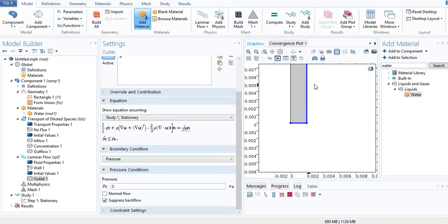To define it as an interface, we know that the velocity on the wall here is zero, and the maximum velocity is at the interface. And for a fully developed flow, the flow will be half a parabola, and the velocity profile will not change with time or with distance along the y-axis.